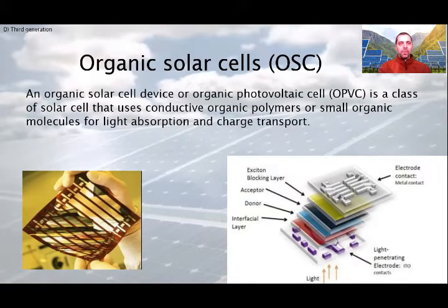They have the potential to provide an earth-abundant and low-energy production PV solution. They use small molecules of organic compounds or polymer to absorb light and consist mostly of earth-abundant elements that can be fabricated into thin films using inexpensive deposition methods such as thermal evaporation and inkjet printing.